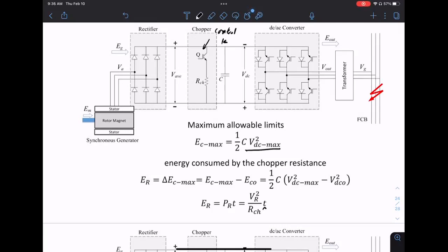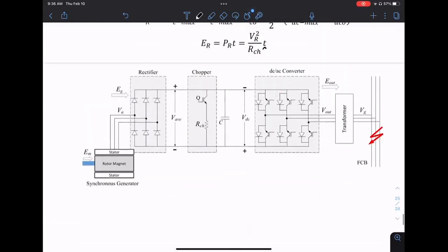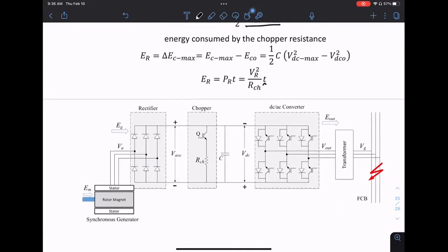Then this RC circuit, that's the assumption. And so if the switch is fast enough, from the capacitor's point of view, it looks like some resistance value, some resistor. And then what we can do is compute how fast this thing needs to switch. So that's the idea of how fast I have to switch.